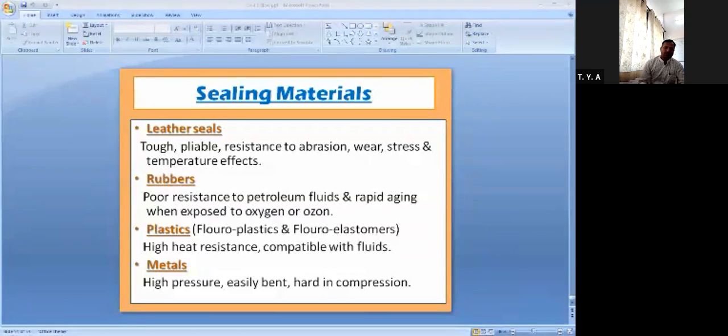Flat copper rings are sometimes used as a gasket, as we know, under adjusting screws to provide the fluid seal. Then molded copper rings are also sometimes used as a packing with gear pumps which operate under high pressure.